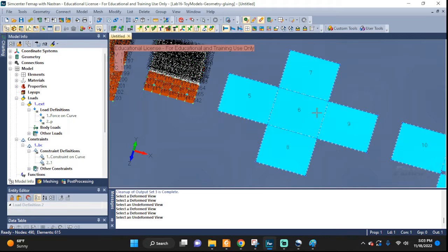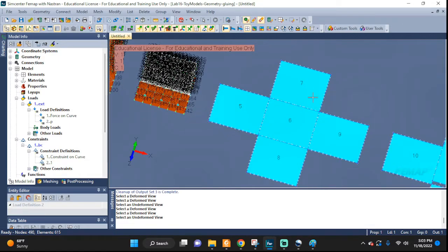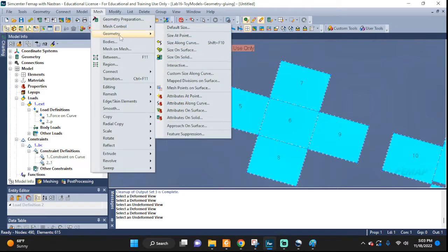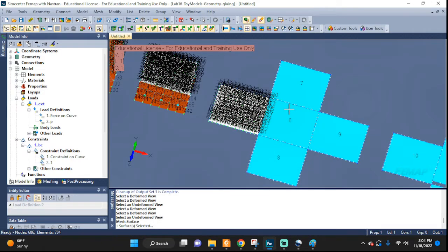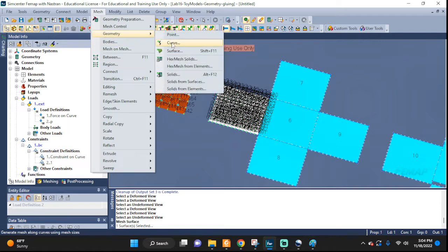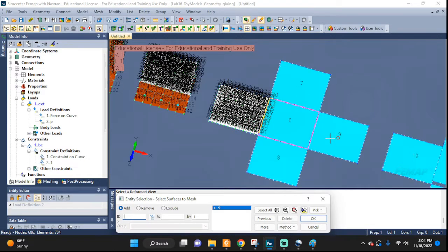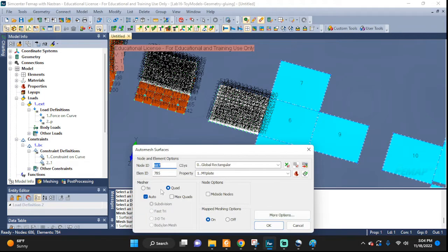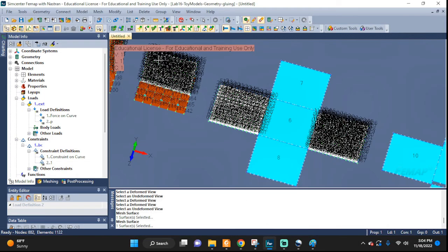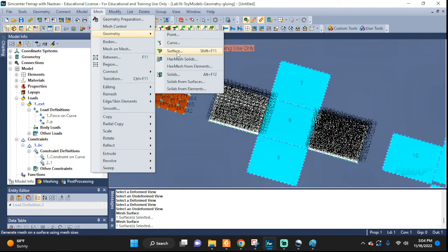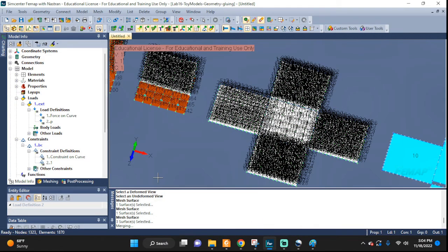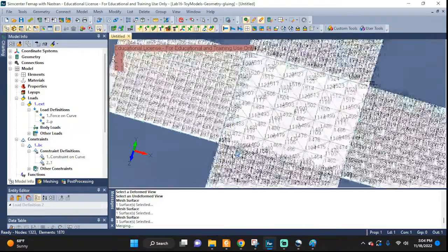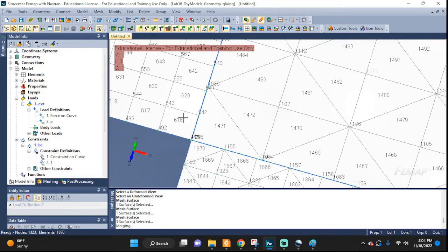Okay, on the next one, let's set up our next geometry. Let's do some mesh. We enter the mesh control. Now we're just gonna mesh this one. Okay, mesh geometry surface. Let's say I'm gonna mesh this one. I'm gonna do that on tri. Okay, and then mesh geometry surface, and maybe I'm gonna do these three together. And I don't know, whatever, tri. There you go. If we look close, I'm pretty sure chaos again. Look at that. Nothing matches, duplicate nodes all over the place, everything.